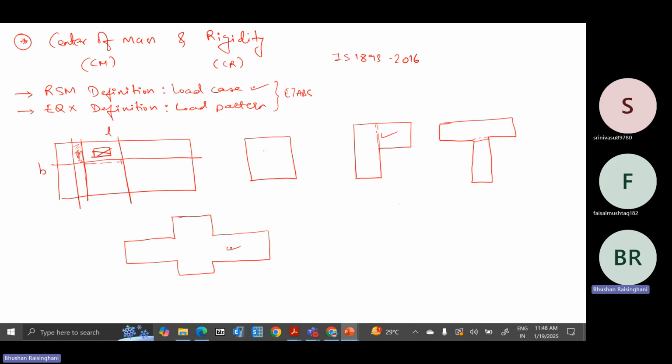However, for a full arrangement, the global picture, if I am having a slab something like this, in which the length is maybe greater than 10 times the width, so this may be 5 meter and this may be 50 meter, maybe like this, or 45 meter at the most. So 9 to 10 meters difference is there. Then what will happen? This will not act as a rigid diaphragm.